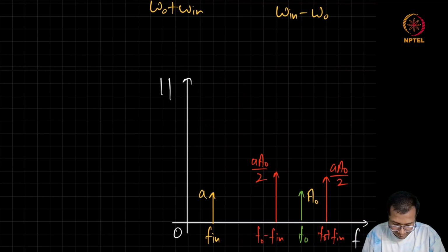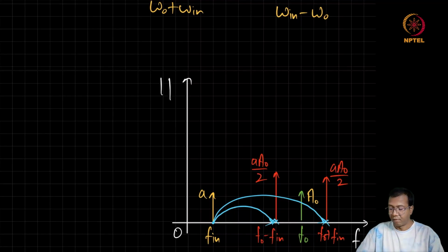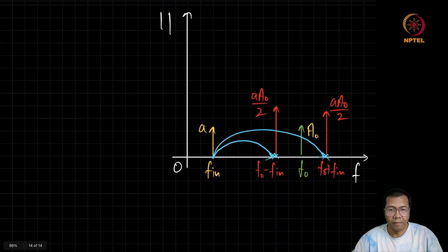And it is very obvious that we started with some frequency f in, and it has given rise to signals at frequency much higher than f in. So compared to the previous approach of nonlinear network, this approach looks much more promising, as it gives you an ability to increase the input frequency to a much higher value with a very simple periodic time varying operation.